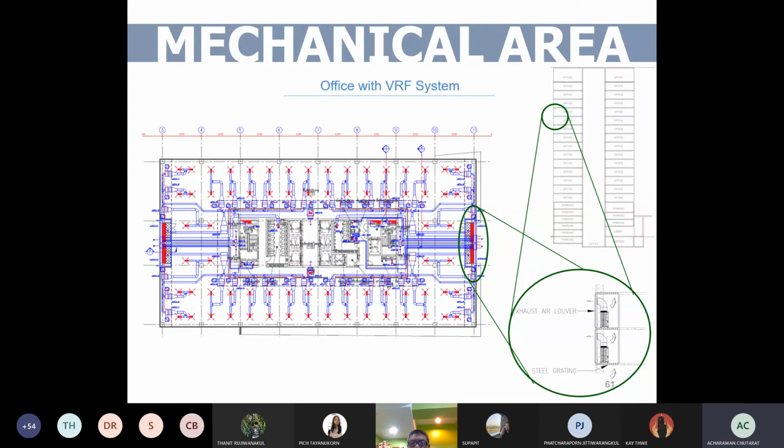Because different owners should have separate meters. But sometimes when you combine everything together and measure by the hours of operation of the fan coil, you can get more benefit if you are the owner, because as I told you, the condensing unit can share the load. When that room is already cold, the electronic expansion valve is closed already, so it does not occupy the condensing unit, but it keeps running, so you can charge them.